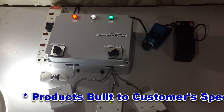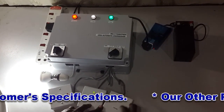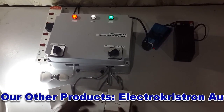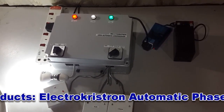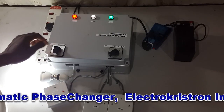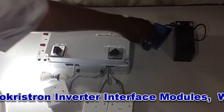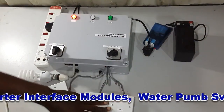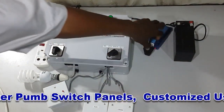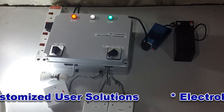For the type 2 generator, you are going to need run and crank indicators, or better yet, run and crank control lines to be connected to the ignition key of the generator, so that you have something like this to start the gen. As soon as the gen has started, the crank command will go off.